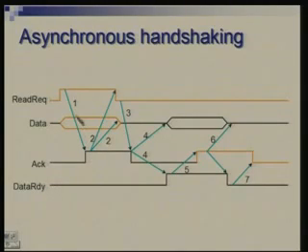This read request could have originated from the processor, or it could be from an IO device. Whosoever had sent this request will keep looking at the acknowledge signal, and when acknowledge becomes 1, then the request can be lowered. So this is a confirmation. This event is a confirmation that the earlier event has been noticed.